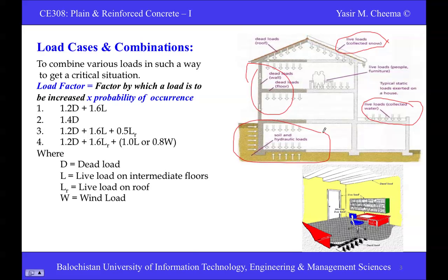Load factor is the factor by which a load is to be increased. If you remember, in our previous lecture, where I discussed the design philosophy and different design methods, I mentioned the difference between the strength method and the working stress method and all these things. I clearly mentioned that in the strength design method, we apply load factors on loading conditions rather than on the materials. But in the working stress method, the factor of safety we put on the material side, but in this method, we put it on the loading side.